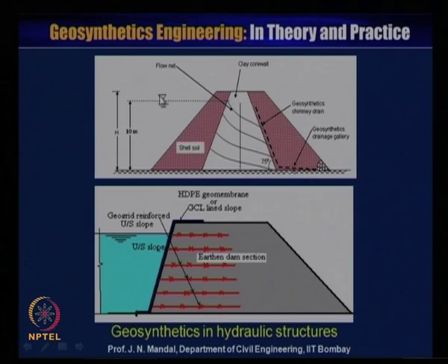So, you have to check what quantity of water passes through this. You can calculate what the water flow will be. You can draw here in the core zone the flow line and the equipotential line, and the combination of flow line and equipotential line is called the flow net.